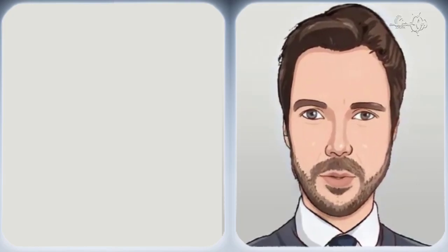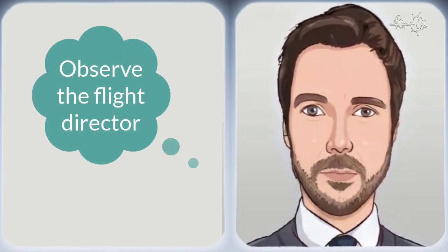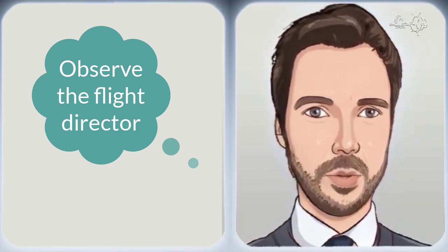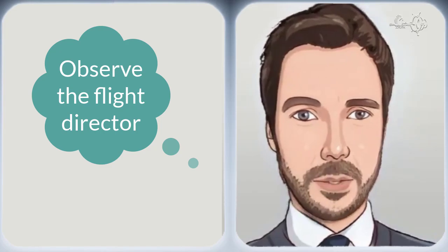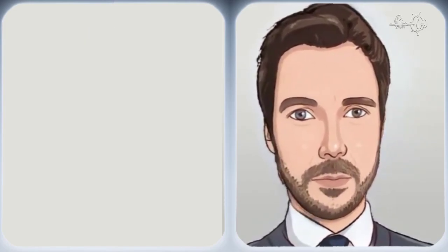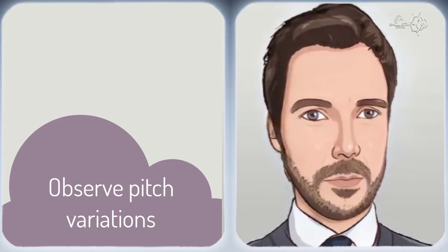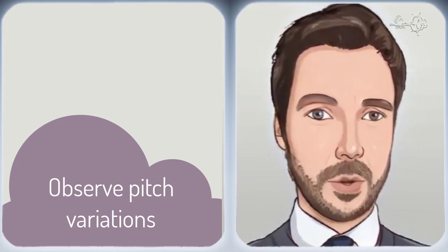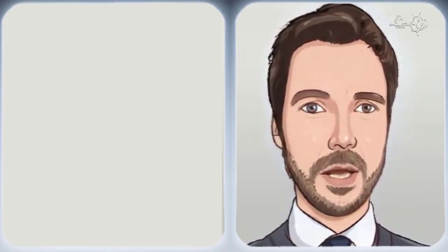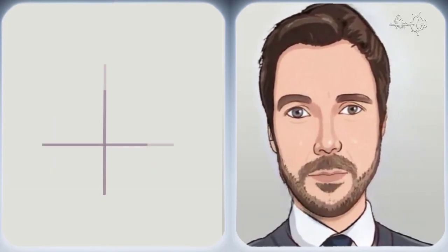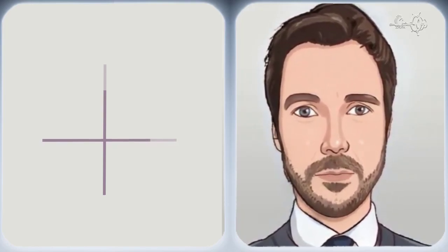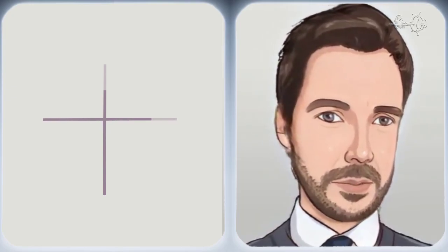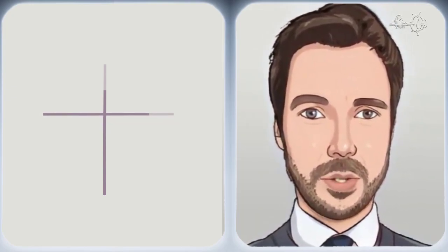May I invite you to further develop your mental database by observing the behavior of the autopilot, as it is a great instructor and usually does a very good task in maintaining the profile. Observe the pitch variations by looking through the flight director anytime you are flying an automated approach. Flying an approach manually, you will then find the confidence to follow the flight director precisely and anticipate the result in vertical speed anytime you change the pitch.